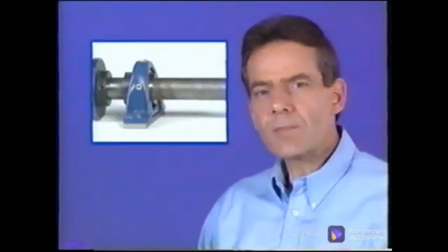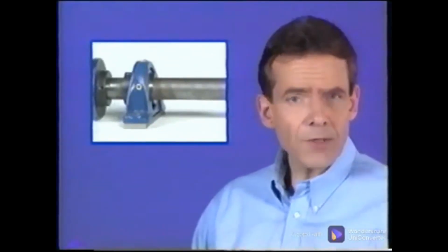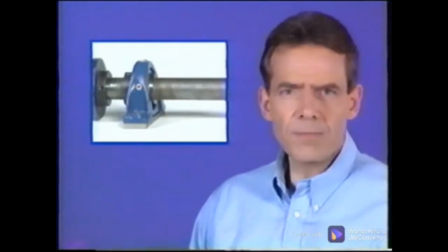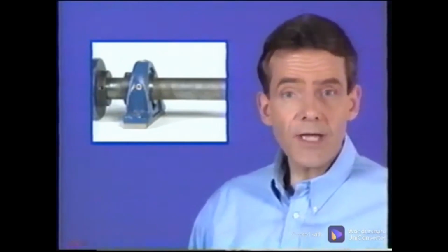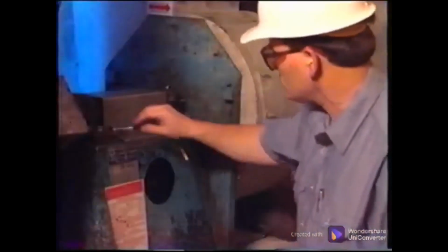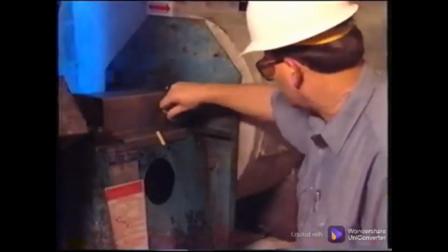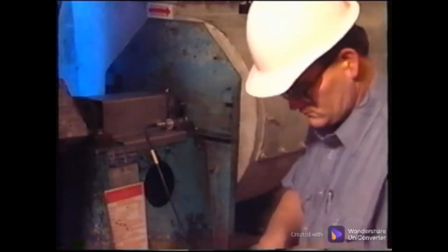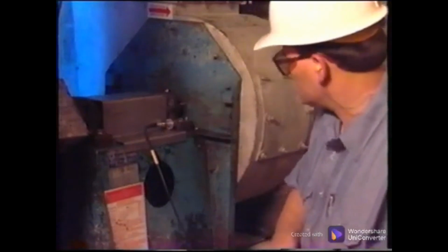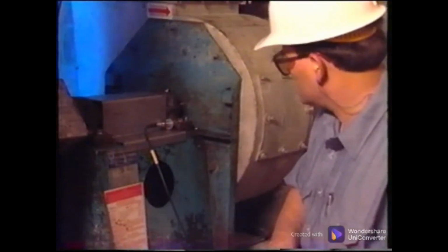Machines that use pillow block bearings require another measurement to accurately diagnose certain problems. There should still be 2 radial measurements per bearing, but an additional axial measurement should be made on each bearing. Since the pillow blocks are independently mounted, it is common for them to be cocked on the shaft. The axial measurement is a good indicator of this problem, as well as early bearing wear due to heavy axial